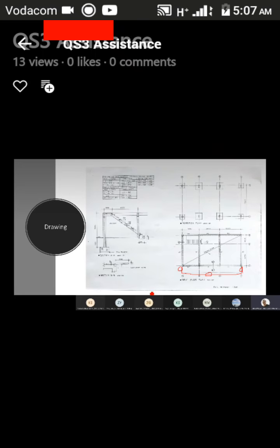But at the same time, I have over-measured my formwork to sides and soffits of beams. When I measured this dimension here in my formwork to sides and soffits of beams, I now need to deduct that there because there's no formwork that would be placed over there. And everybody see where I'm showing where I will be deducting my formwork to sides and soffits of beams as before.